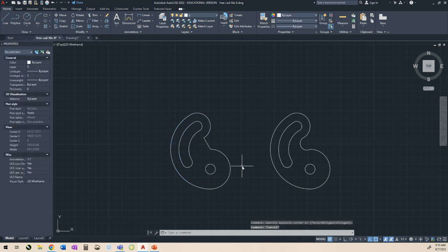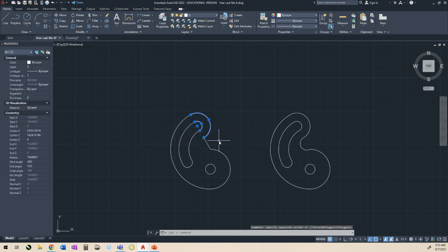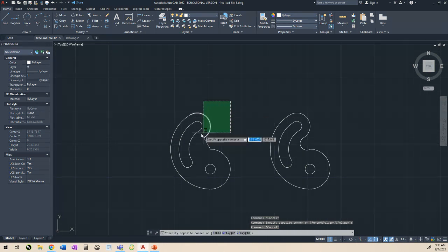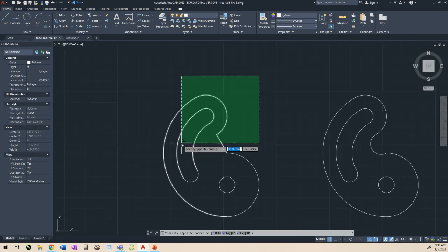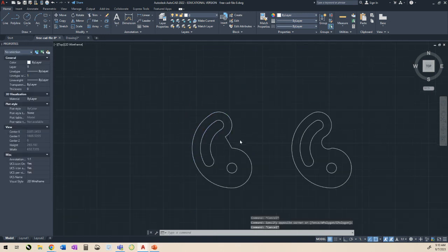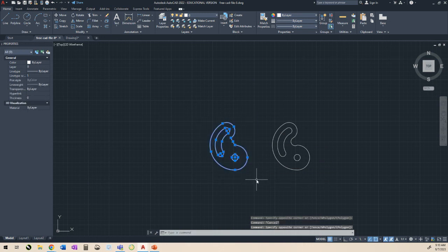With the blue selection box, only items that are completely enclosed in the box are selected. And you can see a little bit ahead of time, see how these are kind of glowing a little bit. That's showing you what is about to get selected when you click.